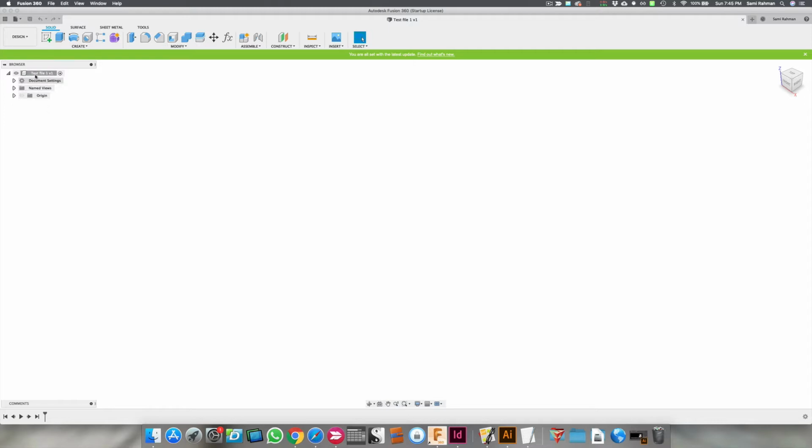So the very first thing you need to do, there's nothing that says parts here or drawings. So the very first thing you need to do is you need to right click and create a new component. If you do not do this and you just start drawing, it puts all the data at the master level. And like organizing everything else, don't put anything at the master level. Everything is made in a folder underneath the master. Because what you'll end up learning is you may draw a single part, but a finished product or whatever may contain multiple parts. And so in your file structure, if you make something that has 3 parts, I would expect the file to have 3 components. And inside those, they can have multiple parts inside that.